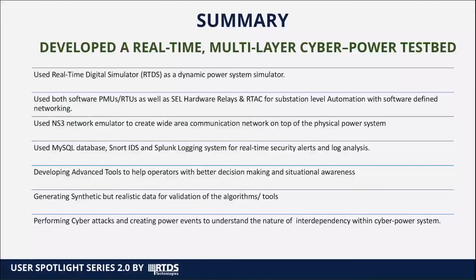So coming to the summary of our work, we have developed a real-time multi-layer cyberpower testbed where we have used a real-time digital simulator as a dynamic power system simulator. We have used both software PMUs and RTUs, as well as SEL hardware relays and RTAC for substation level automation with software-defined networking. We have used a network simulator to create a wide area communication network on top of physical power systems. For logging and data storage, we have used MySQL database, Node IDS, and Splunk logging system.